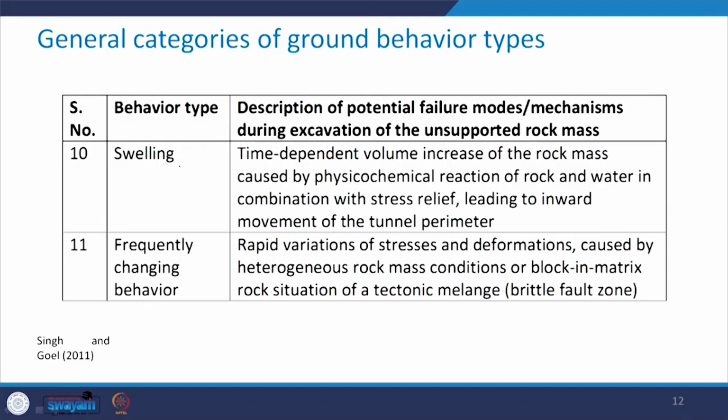The next behavior type is swelling, and it involves time dependent volume increase of the rock mass, which is caused by physico-chemical reaction of rock and water in combination with stress relief, and it leads to inward movement of the tunnel perimeter.